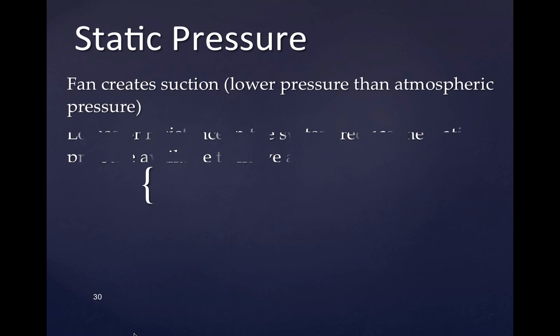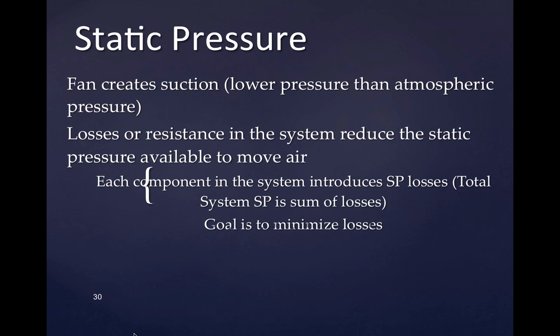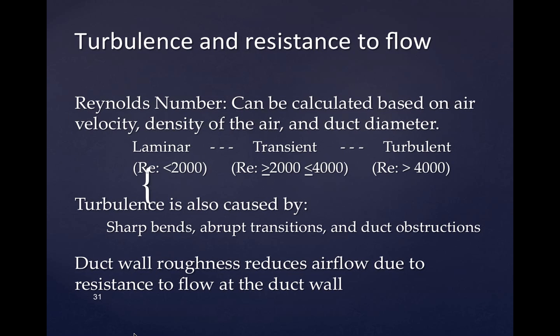So in order to make the hood operate right, you have to go through the entire system and design it so that you make up for any losses in transitions, elbows, duct friction, fan losses, hood entry, and so on and so forth. The whole reason for the fan is it creates that suction pressure, right? It imparts the energy into this whole thing that keeps things moving.